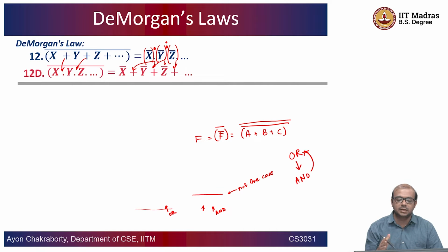But in this case, this is a particular law called De Morgan's law, where the complement sign over the entire expression could be broken up into complementing individual values and replacing the OR operation by an AND operation. This is a very important result for simplifying Boolean algebra expressions. Okay, so you'll come across this thing very frequently.